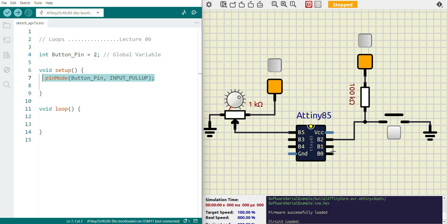In digital electronics, we have 0 or 1, ideally. But in the real world, real components are susceptible to temperature changes, electromagnetic interference, and very many other things that exist in the real world, that we do not base on in the ideal or theoretical world. So you will find that a GPIO does not have a definite state, not until you define it. It can have a floating voltage. Remember, we have what we call logic levels.